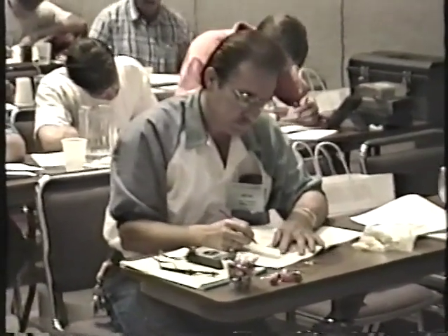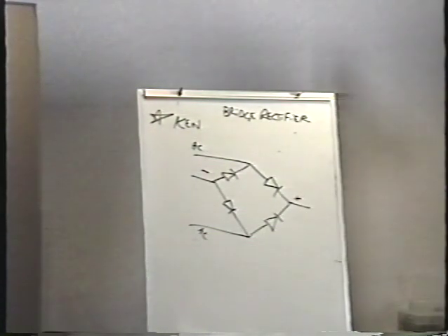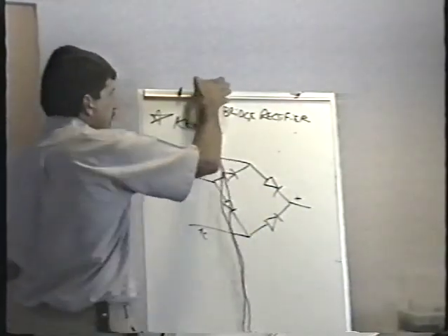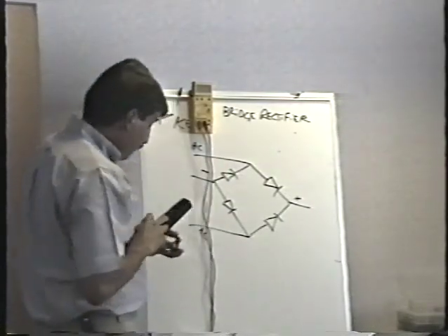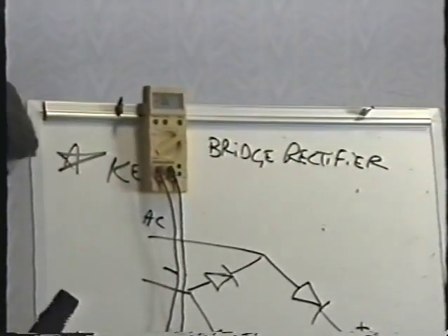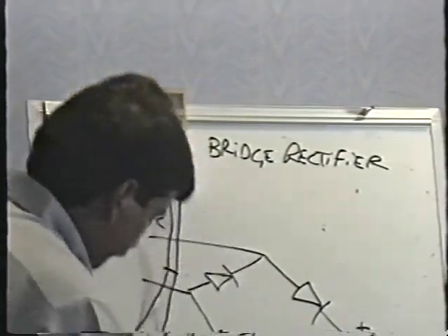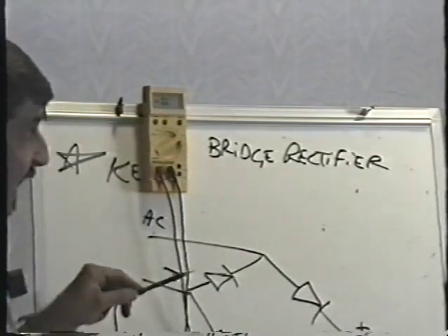But it's very easy to test the bridge rectifier to see if it's good or bad, because all you have to do is test it as if it is 4 individual diodes. And again, you're going to use the diode test setting on your meter. Let me check what I believe to be a good one here. And all I'm doing here is checking each.